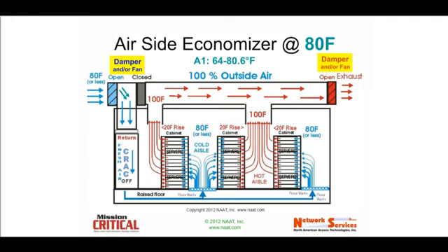It's being directed by the vents and fans on the top side units into the cooling unit, but notice it says the CRAC is off. We're basically pushing the entire airflow from the outside through the unit into the floor, essentially using only the fans to push that air. The CRAC is off at that point.